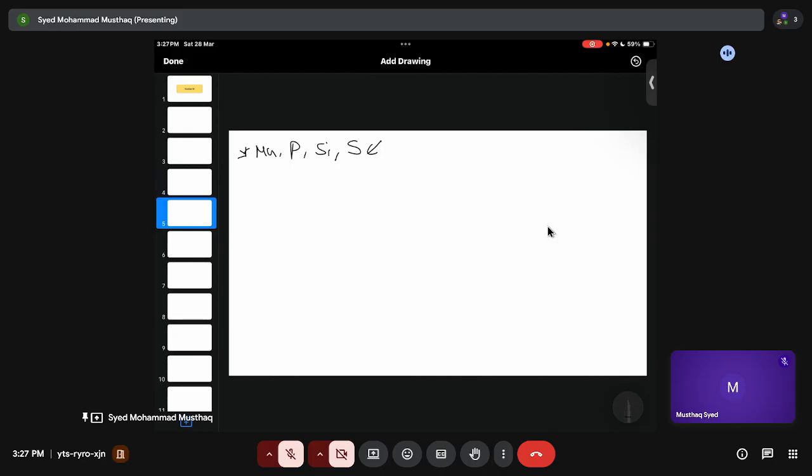Okay, so basicity is nothing but we are trying to add calcium oxides. So basicity is nothing but the oxides which can donate oxygen atoms, right? So adjusting basicity of slag, and again the temperature. So let's say the phosphorus pentoxide that is present in solid will be reduced by the coke to give you phosphorus and carbon monoxide, right?